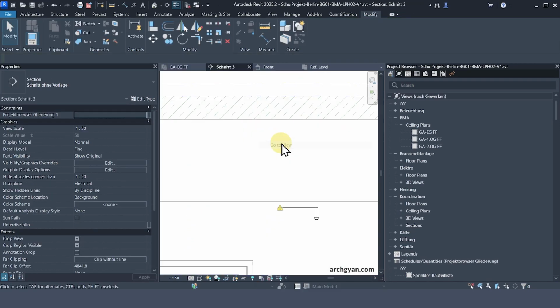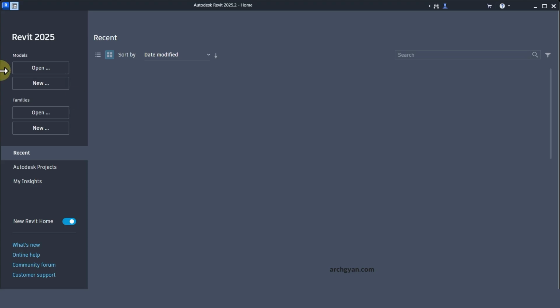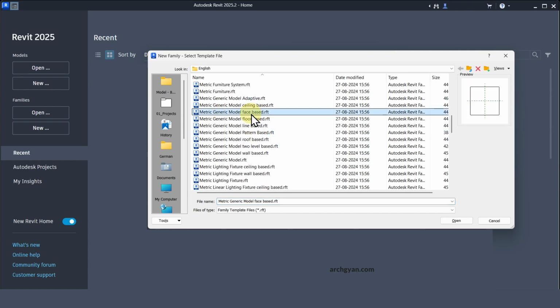In this video, I'm going to show you step by step how to create a sprinkler family in Revit. Let's go. Alright, so the first step is to create a new family. So let's click on new. In our case, let's go with metric generic model face based.